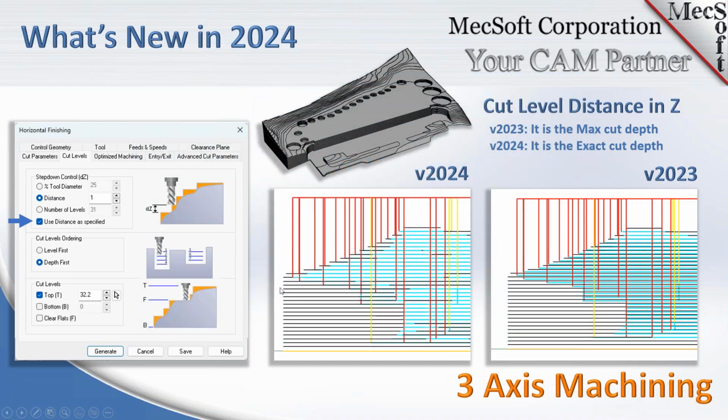Now this one, I like this one as well because previously, if you may have run into this, if you're doing 3-axis horizontal finishing, you didn't always have exact control over the distance between the cut levels. Correct me if I'm wrong, Joe. It calculated the overall distance and then overall cut depth, and then divided that by the maximum distance, and then it would fluctuate in between that.